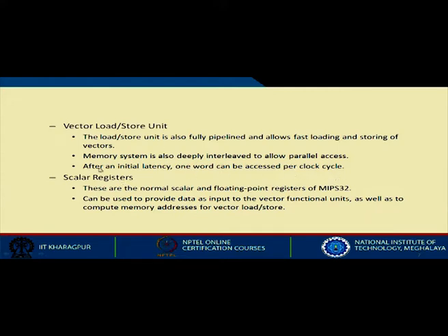And in addition to that, the scalar registers are also there, like in MIPS32. These are the normal integer and floating point registers. Now, these registers can be used to carry out integer operations, of course, but they can also be used to provide data as input to the vector functional units.